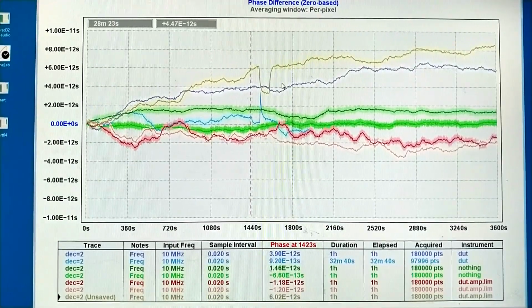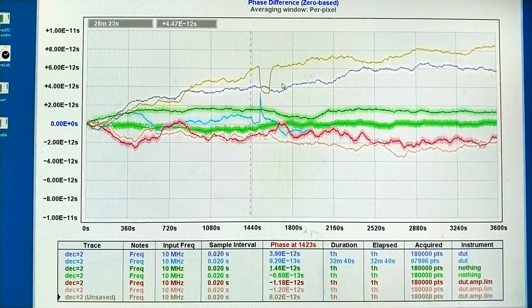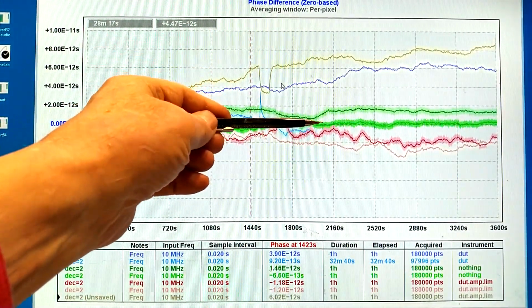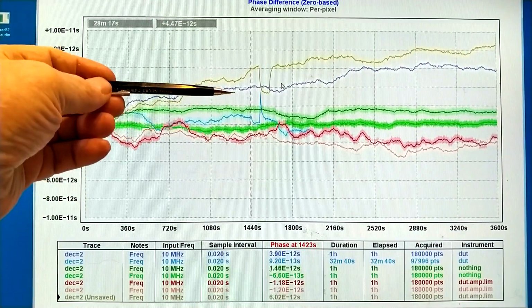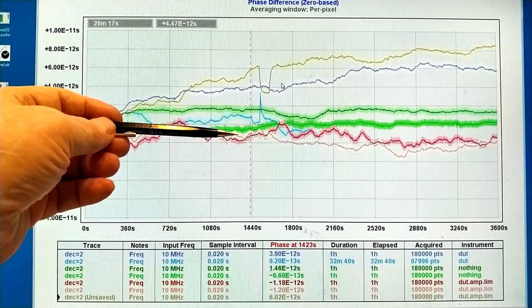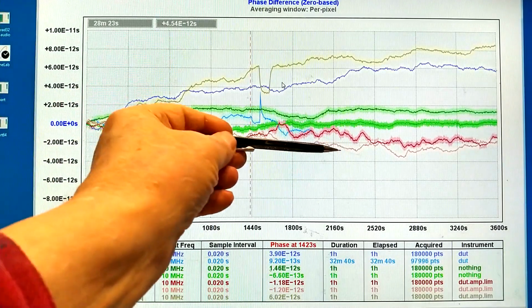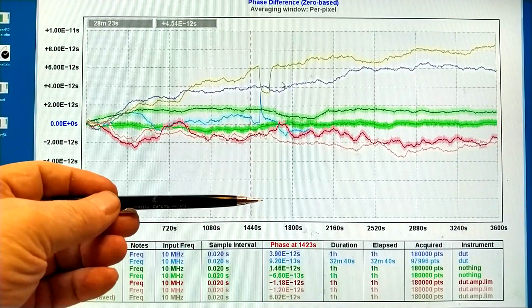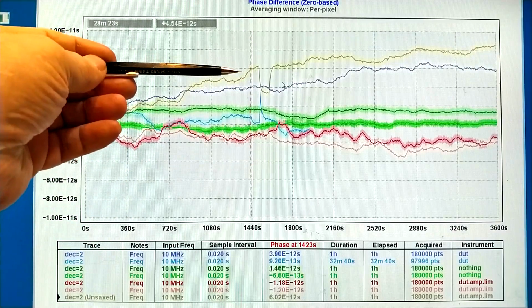I have made a couple of measurements on my selective amplifier, and also with the female BNC adapter. So the green trace is when there is no amplifier, just the adapter, and it is obviously calmer than the other traces. And then the red and brown, this one and these, they are with the amplifier, both amplifiers and the limiter in the limiting mode. And the blue traces are with only the first amplifier.